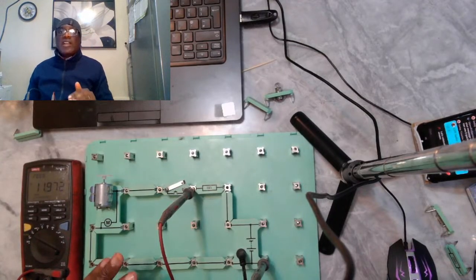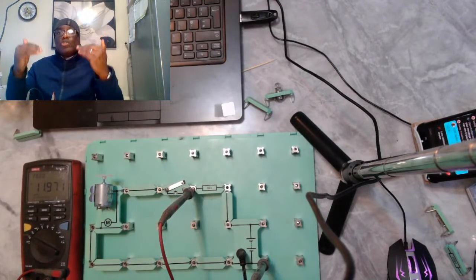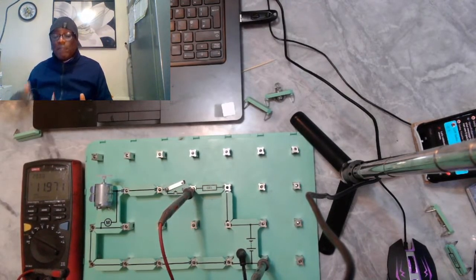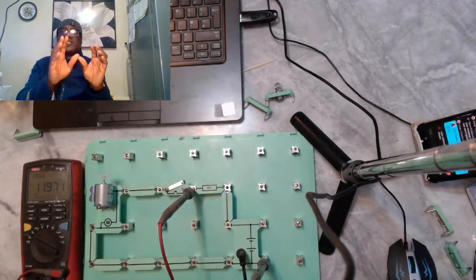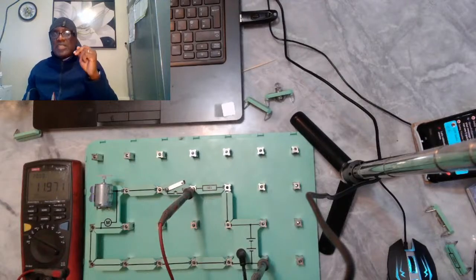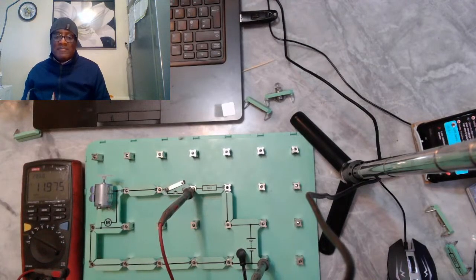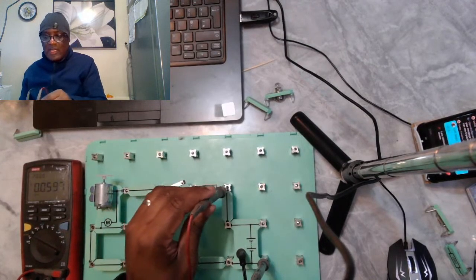And because of what? Because the voltage that drives it has dropped. The voltage that is the one that pushes the current in a circuit has dropped. So that's the reason why we are in this situation where the motor wasn't turning. All right? But we have seen here that,